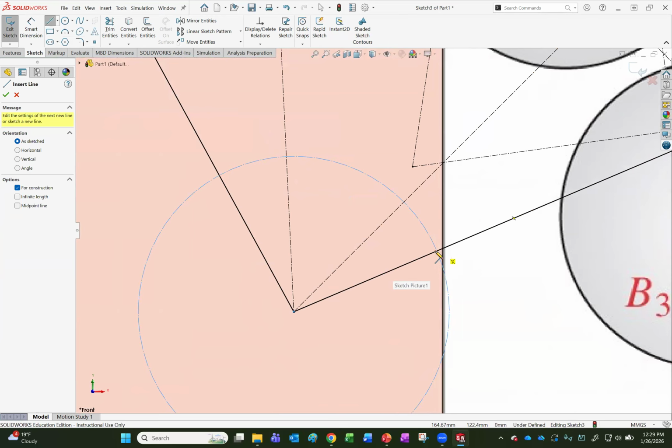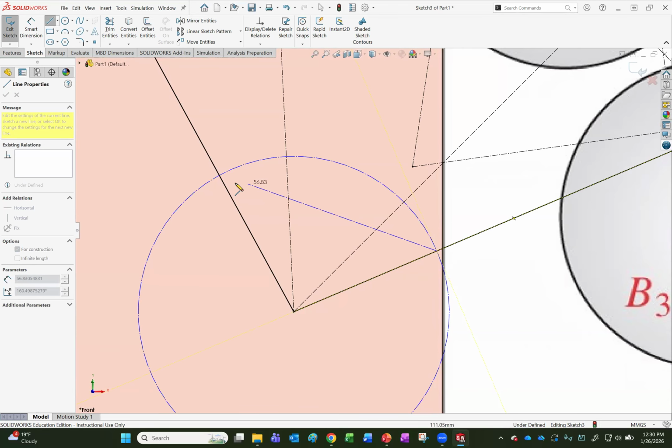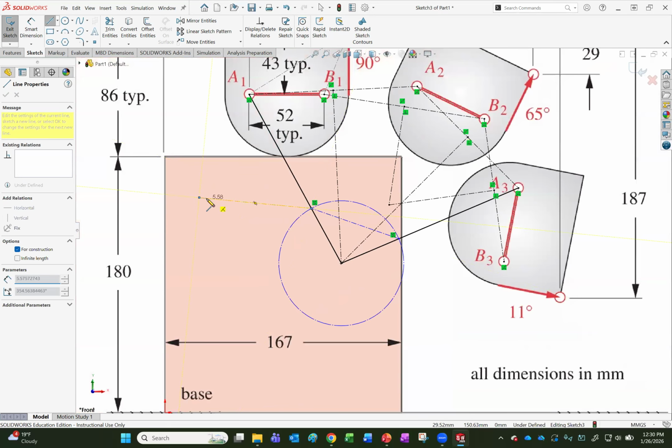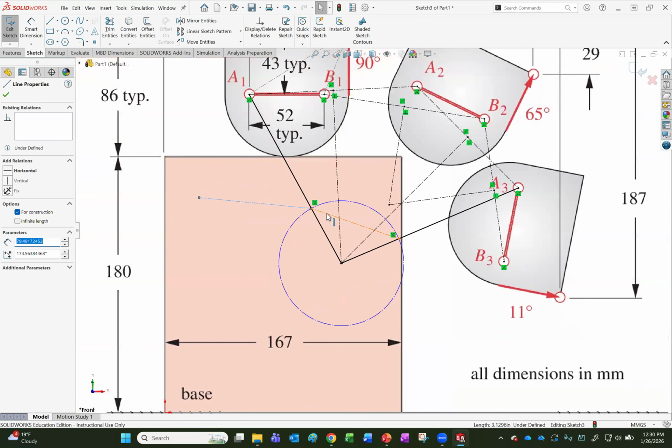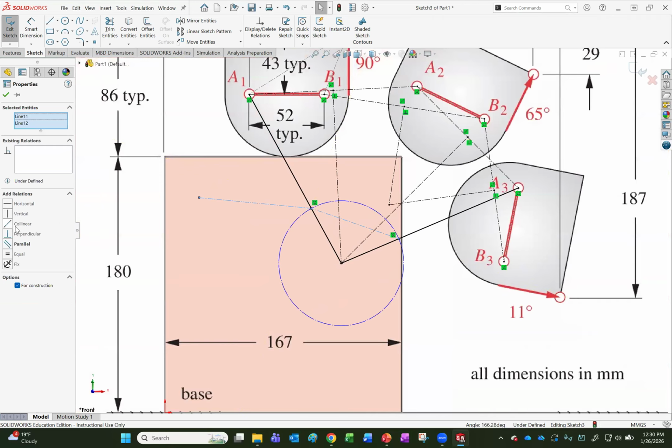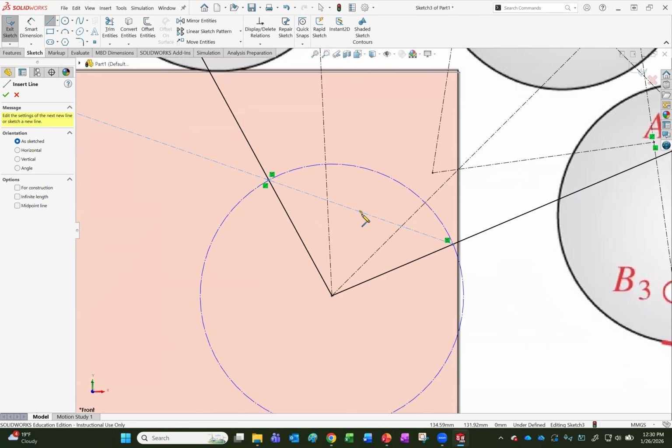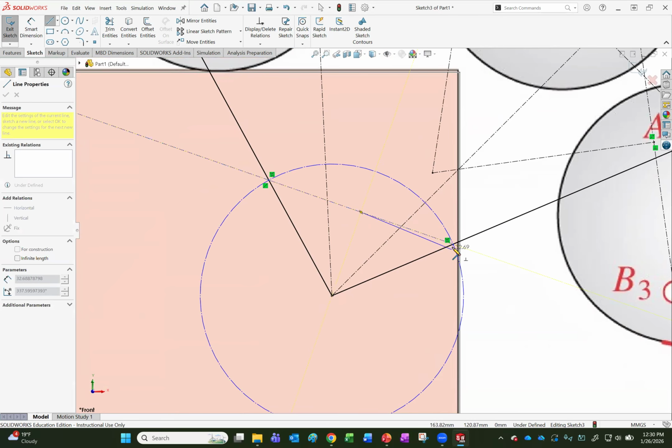I'm going to find the connection. You can see that little relation is turned into an X looking thing. Another one right here. Okay, got it again. And I'm going to extend that line. I'm going to make a line there, and I'm going to make him coincident, not coincident, collinear. And then I'm going to make a solid line from the center to over here.